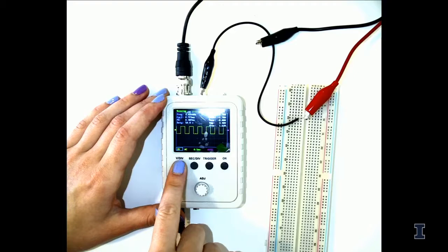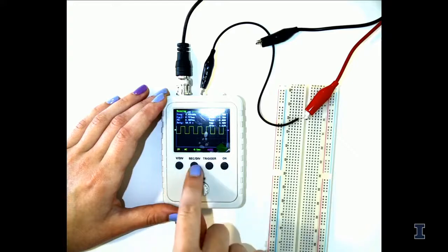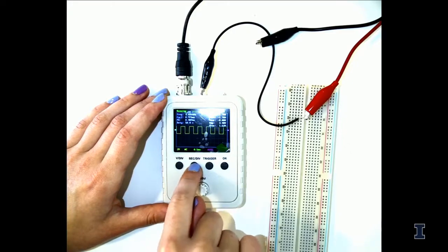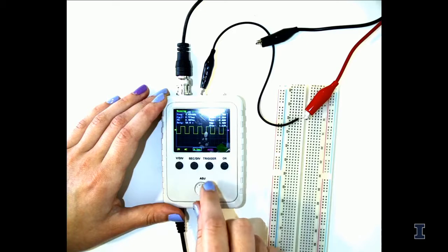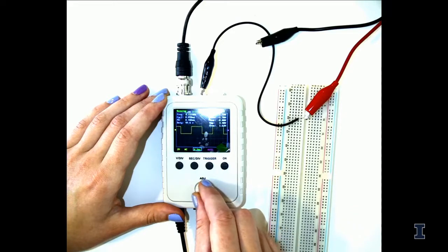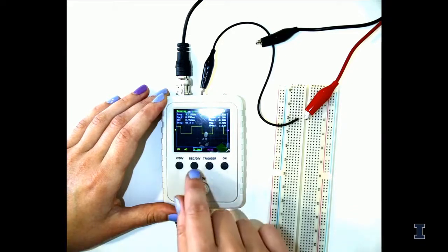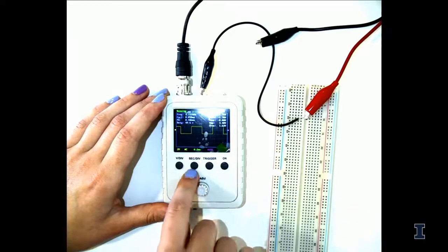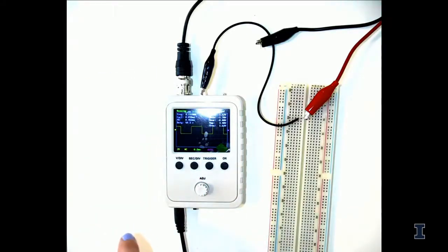When you're done adjusting your voltage, you can just press it again, so it's unhighlighted. And then if you go to the second division here, and you turn the knob, you'll see it spreads out or gets closer together. So your x increments are changing. When you're happy with your signal, you can just press second division again, and it locks into place.